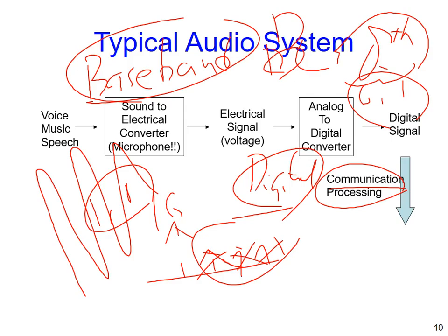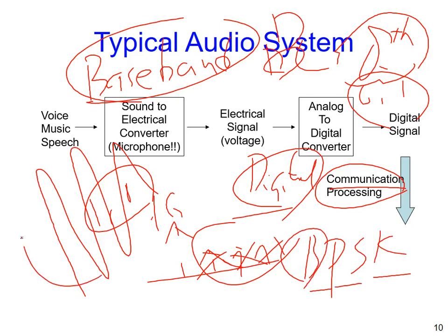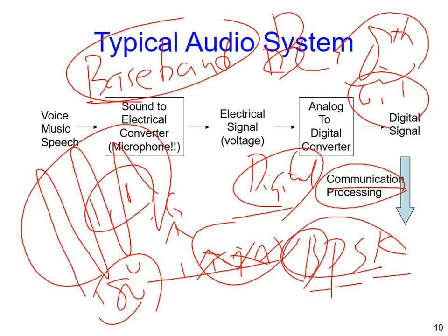For example, we have the so-called BPSK, binary phase shift keying, with the same sine wave, but 0 degrees for 0 and 180 degrees for 1. That is the way we can transmit digital content on an analog sine wave. The same 1 gigahertz sine wave, but with different phases.